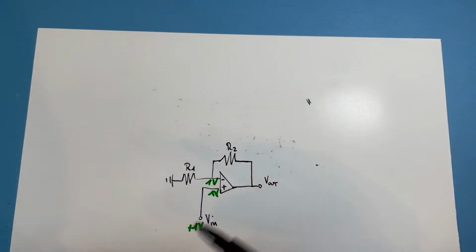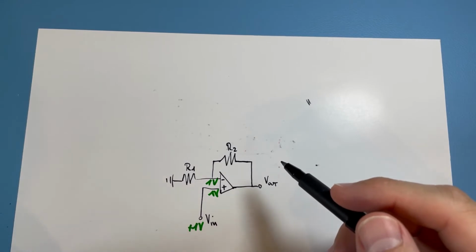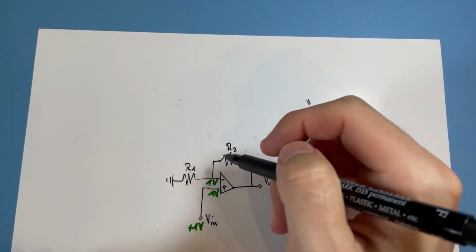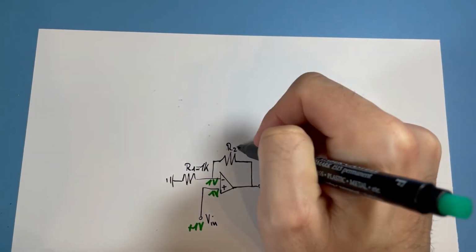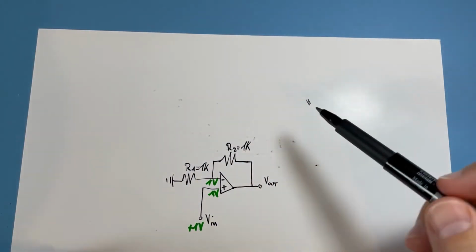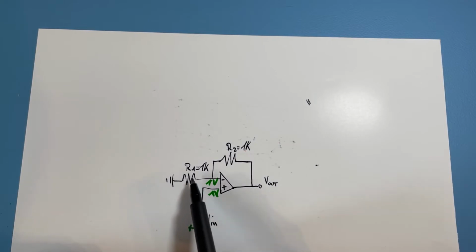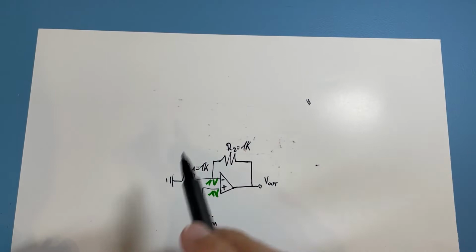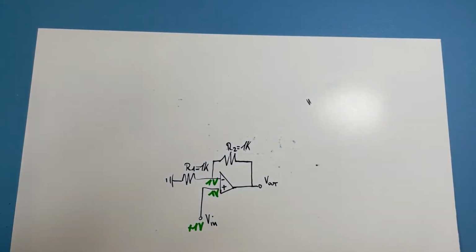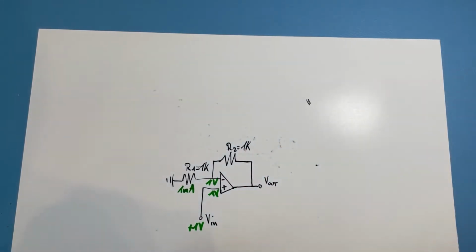And let's just imagine for the moment both R1 and R2 would be, let's say, 1 kilo ohm. So R1, let's assume it to be 1K for the moment, and R2 to be 1K, just to be easier for explanation. And then what would that mean? That would mean you have 1 volt dropping down to ground over this resistor of 1K. So there must be 1 milliamp flowing through this resistor here. Let's draw it in this way, 1 milliamp.